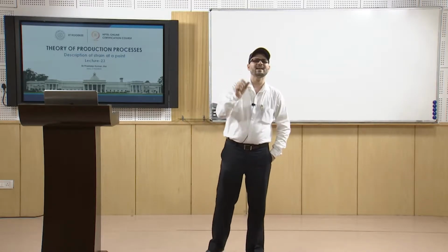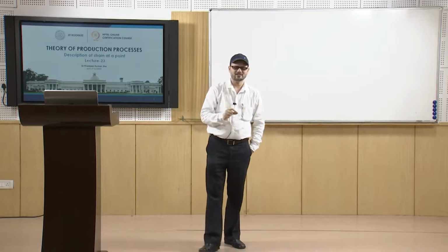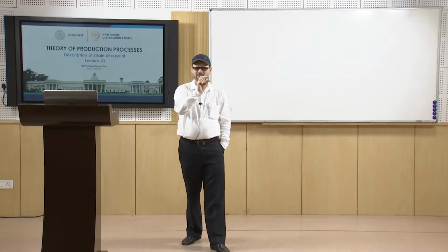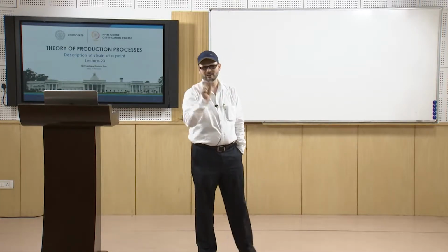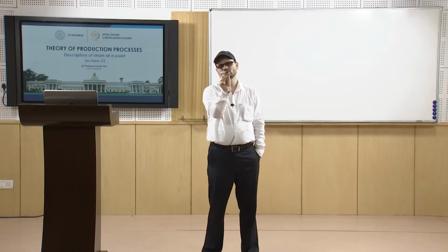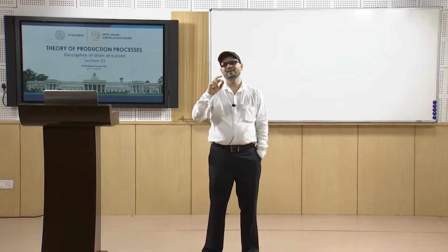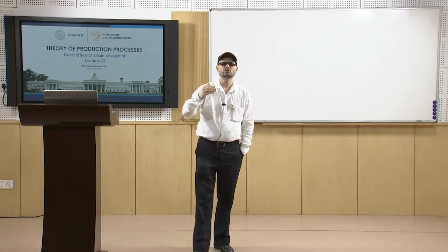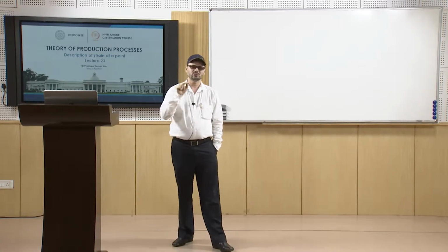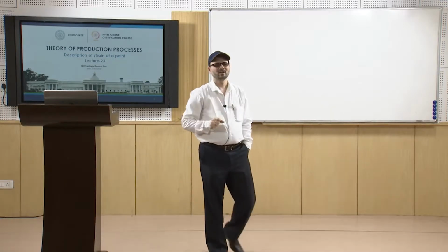If you take the x direction, suppose the displacement for point A is u, and for point B it will be u plus dou u by dou x into dx, because dx is the distance.